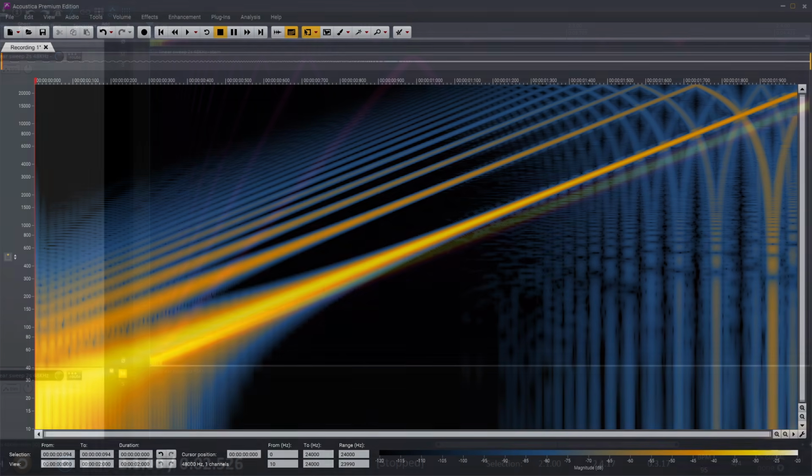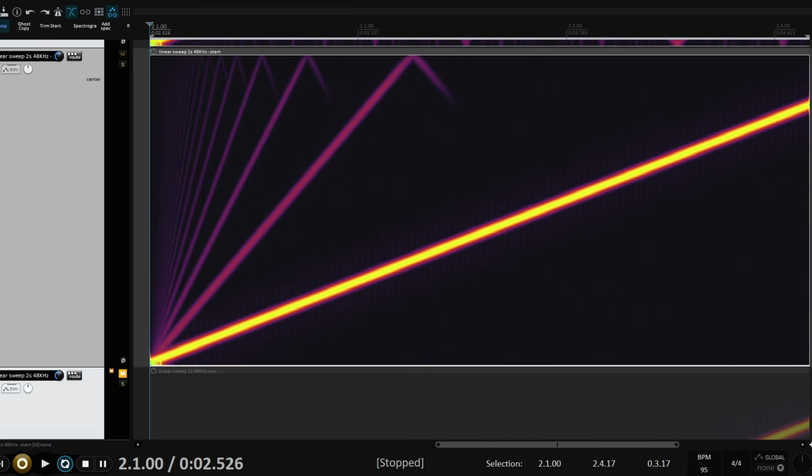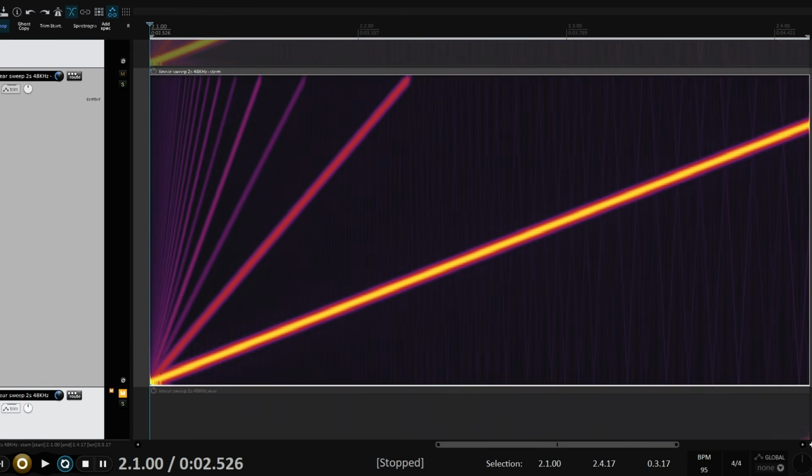Anyway, if I turn on oversampling, those reflections disappear, and we get a much cleaner, more authentically analog response. Different developers may have different opinions as to the optimum settings for the anti-aliasing filters. Sometimes the harmonics will fade out just before they reach the Nyquist limit, indicating a slightly lower filter cutoff.